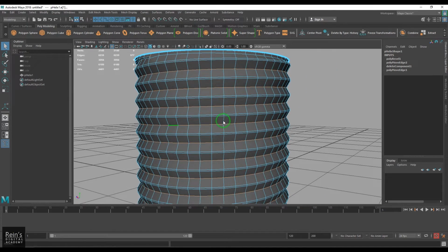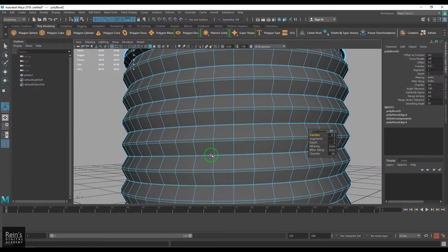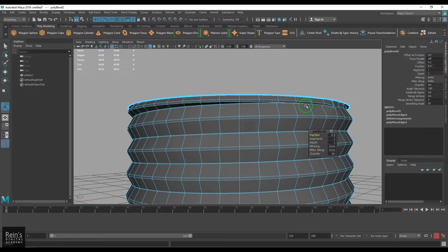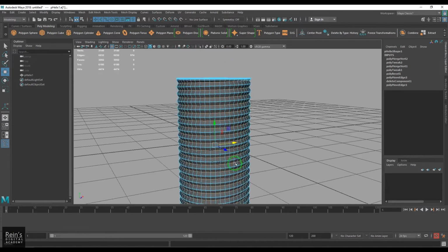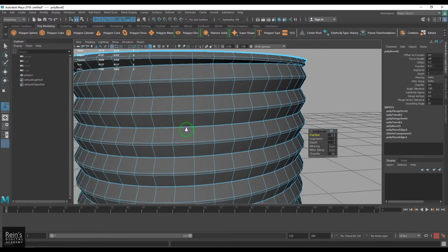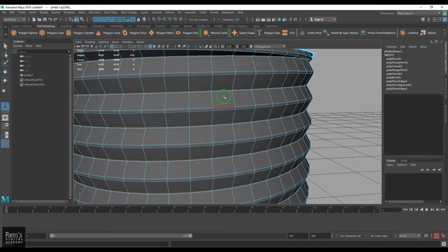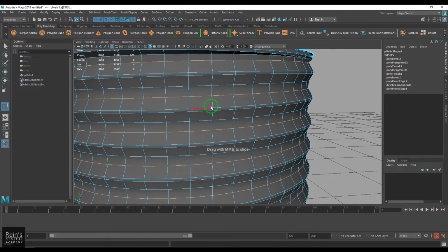Okay, this bevel radius might not give you a bigger radius here because this is controlling the size of it. Then I'm going to select this line, and I'm going to apply bevel. Okay, and then use this slide edge tool on both sides.